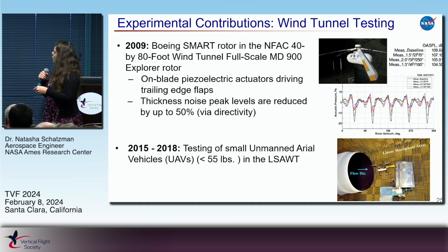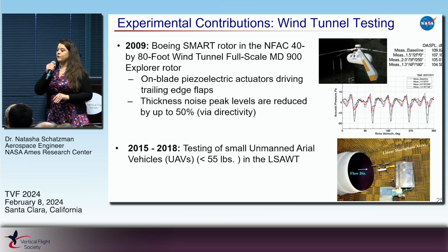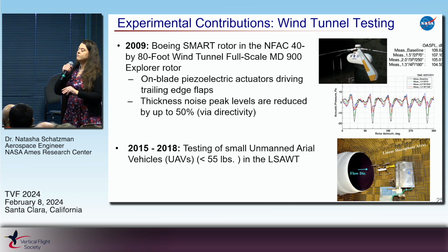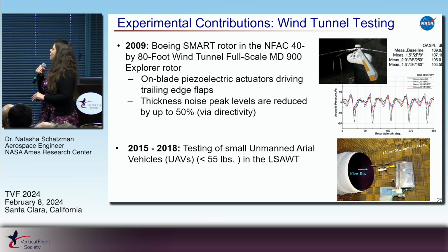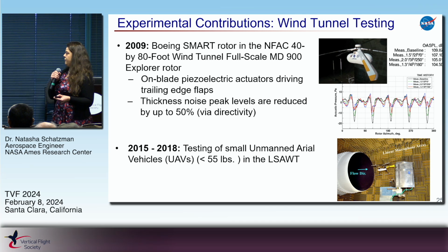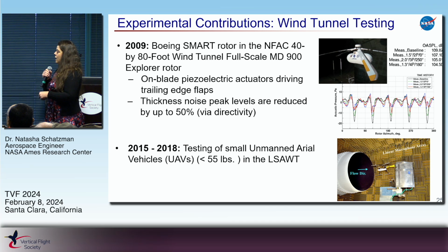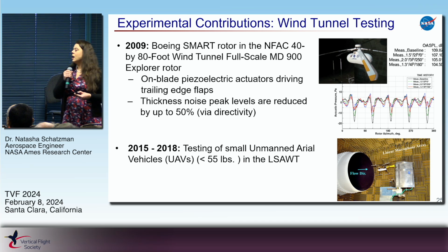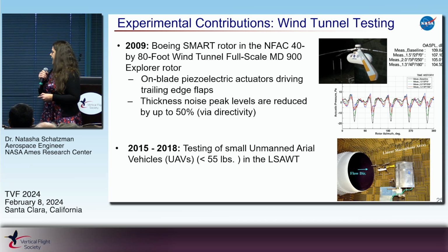One thing that came from this test was a reduction in thickness noise, the noise radiated in plane of the rotor, that monopole source term, which was reduced by 50%, based on directivity at a microphone. Then, from 2015 to 2018, various small unmanned aerial vehicles, UAVs, less than 55 pounds, were tested in the LSOT at NASA Langley.